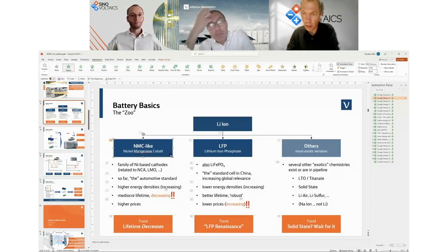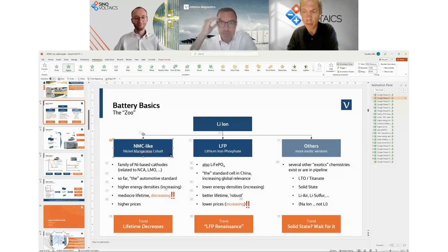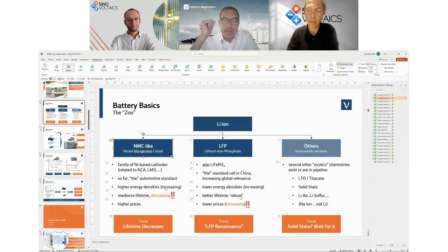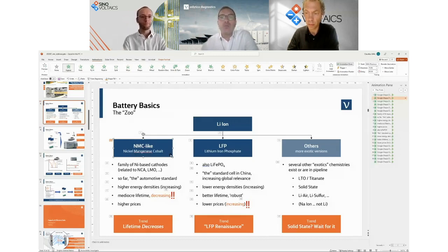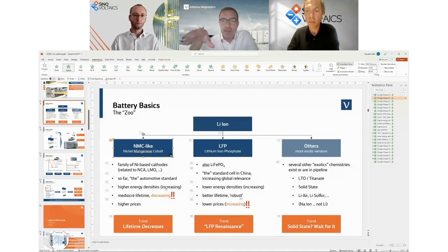You might hate me. I'm like a lawyer, and again, I have to say it depends. It depends on which cell type you're implementing. If you use a cell type that is optimized for fast charging, then you can use 2C, 3C. But again, to not just answer like that, the lower the C rate, the better. Anything like normal technology is anything below or equal to 1C in charging and discharging is absolutely unproblematic.